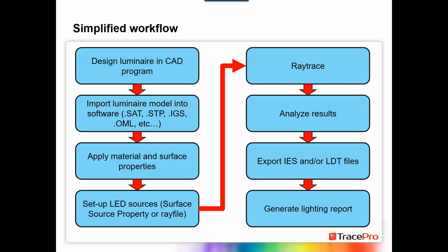I set this up using LEDs as sources, but setting up your sources is not unique to LEDs. It would apply whether you're using an arc lamp, an HID lamp, a xenon lamp, or a fluorescent lamp. You would need to set up that source accurately, whether it's using something like a surface source property or downloading a ray file from the manufacturer. And then you'd run a ray trace.